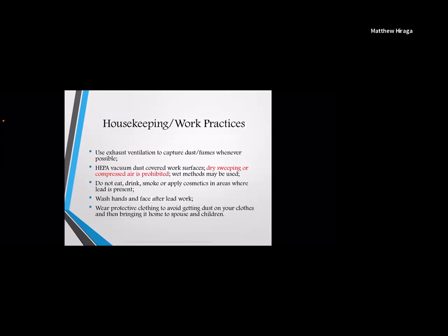And this kind of reminds you that when you're creating your work area, you need to delineate that work area far enough back from exposure, and basically anything within that caution tape, you should not have your water bottles, you shouldn't have your bag of lunch, whatever it may be, food, you shouldn't be smoking within that area. That is a designated working area. Everything else has to happen outside.